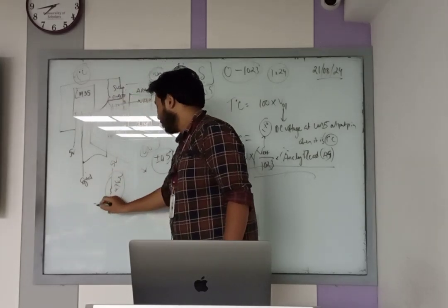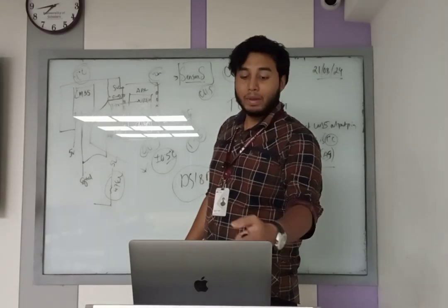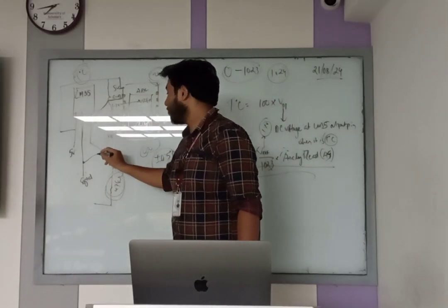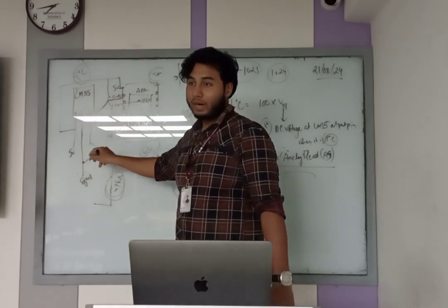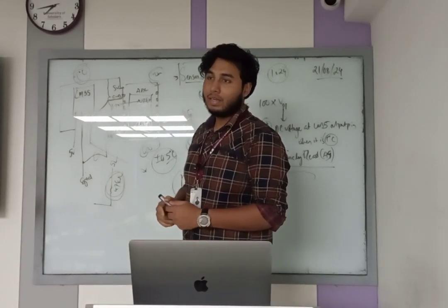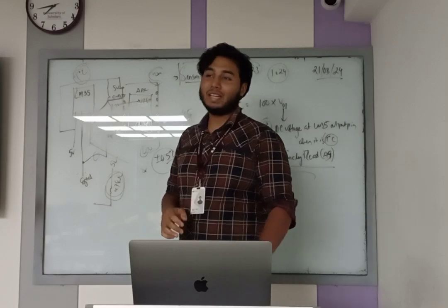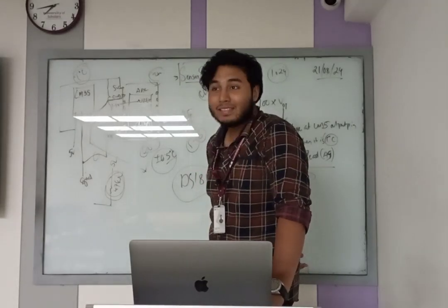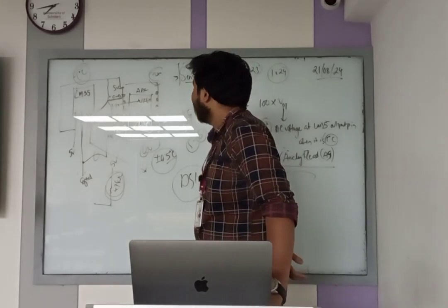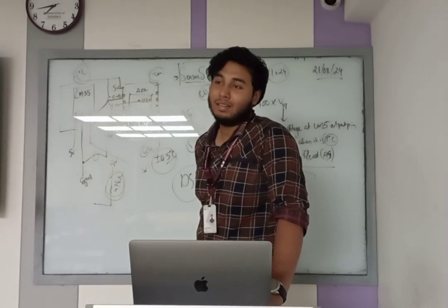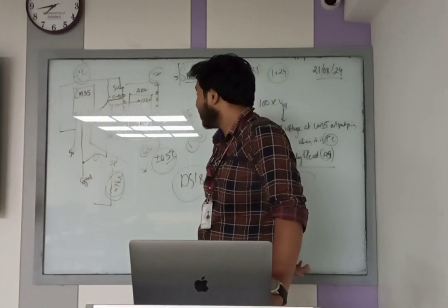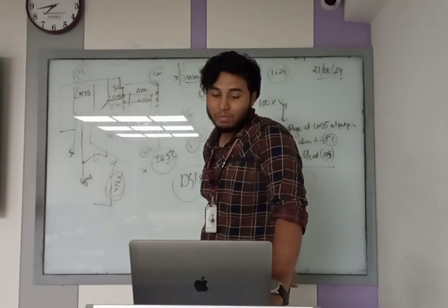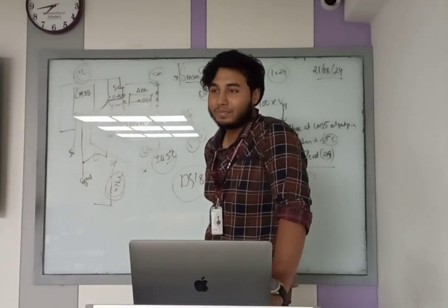Because the 5 volt is connected over there, there is a current drop, and a specific voltage will be occupied through this wire. In analog, we don't have any concern with that. But in a digital sensor, you additionally connect a resistance from one end to the other end, that is, between 5 volt and signal. The same connection and everything will be the same.